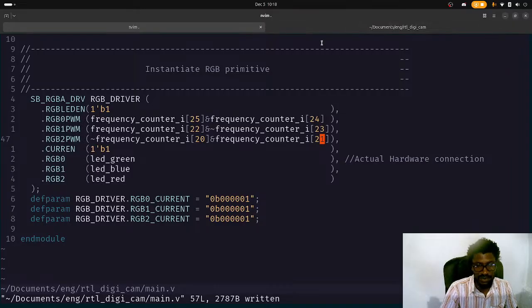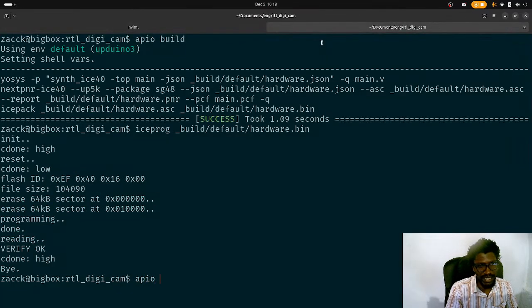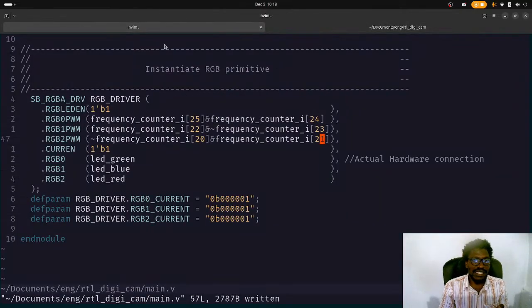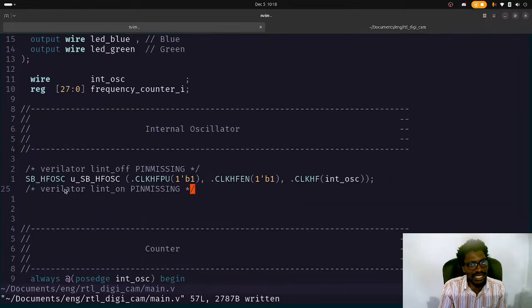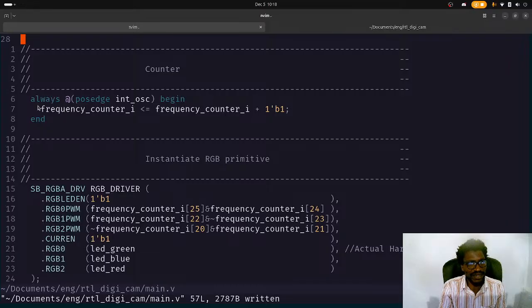Let's actually look at what happens when we do this, and what we're showing here is a digital output, which is basically synchronization. There's a bunch of circuits that are agreeing to do things based on another digital circuit by itself. So there is a clock that is counting, that is filling in bits. Remember, we declared a 28-bit register here, and as this 28-bit register goes on, this is a binary counter.